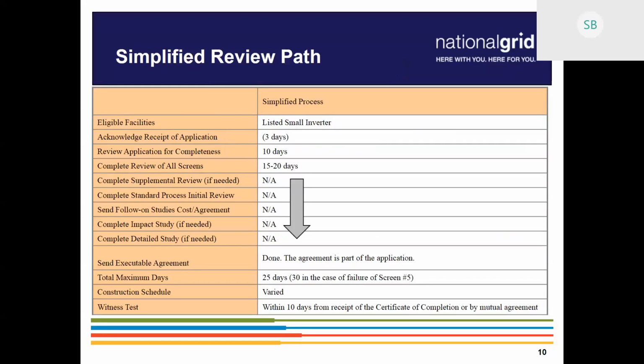With Mass Smart, there is also the service upgrade form for adding that new meter socket, tracking the municipal inspection. We do recommend you submit that service upgrade form before the rest of your completion document, because that way you can get that work request number back, get it to your inspector when he's out there, prevent those multiple calls back and forth, and it just helps the process run smoother if you get that back to us.